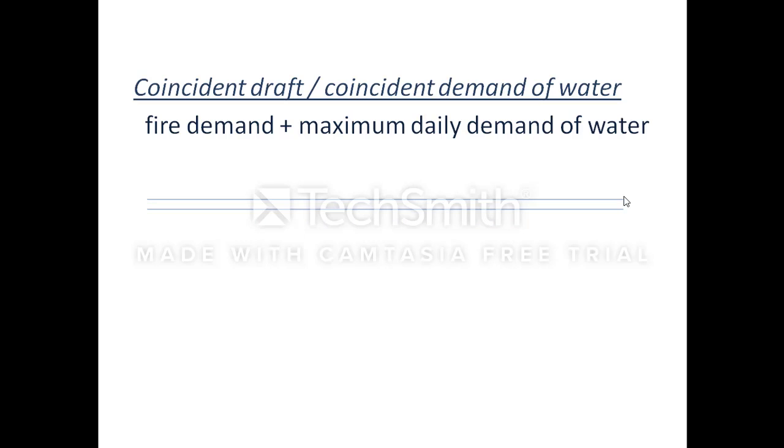Now, what is the coincident draft or coincident demand of water? During fire, there is a certain increase in demand of water. So, for firefighting, besides the usual demand of water, provision should be made to meet the fire demand. So, the maximum demand is added to fire demand. The coincident draft is the maximum demand during firefighting. Or in other words, we can say the coincident draft is the fire demand plus maximum daily demand of water.